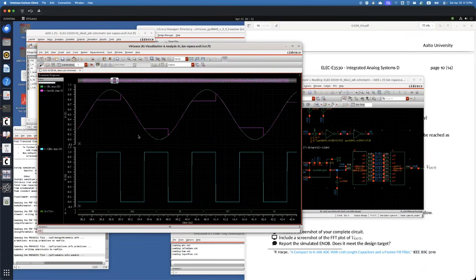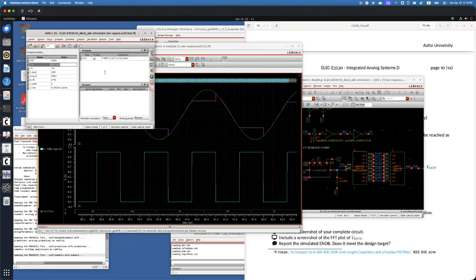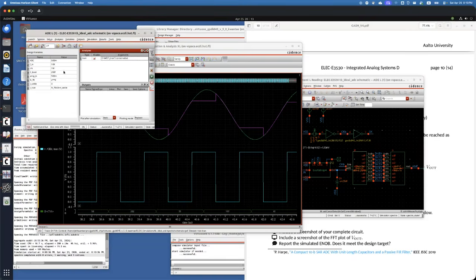And if you zoom in, then you can see that those values are updated 25% later than the leading edge of the clock bar signal, as we intended, as we set the delay as 25% of the clock period. So this is not intuitive for analyzing whether these digital values are correct or not. For that purpose, maybe I can set a very slow signal, for example, 10 kilohertz. How about this one? And let's run the simulation again.